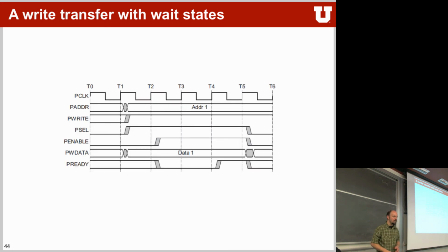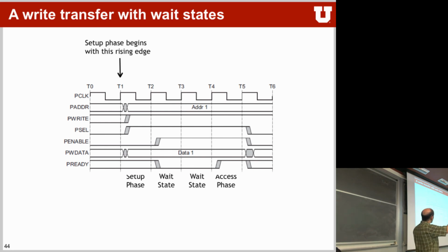You do have a wait state still. So APB can wait and can tell you to wait. In this particular case, it's the ready line. So we have the setup phase over here where everything gets set up. We set up the address on this clock edge, if it's a read or a write, and which peripheral gets selected. On the next one here, we get the enable phase where this line gets pulled up and basically means you can now go and access your data. We have the data down here. We can pull the line down telling it that, hey, wait, this data hasn't been picked up yet, until the line gets pulled up, and then in the next phase, the access phase is done and the data disappears. The bus gets let go and the next phase can happen over here.